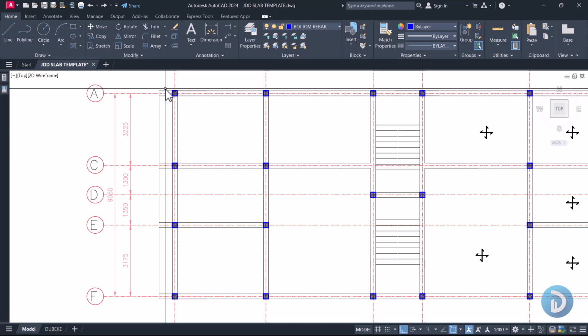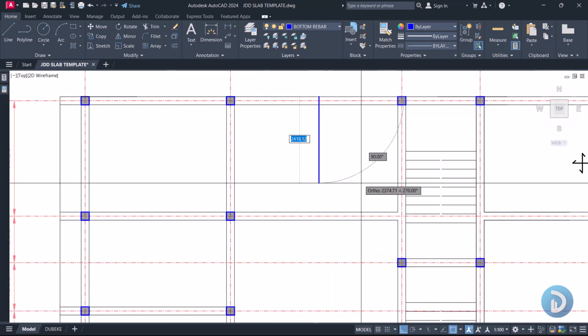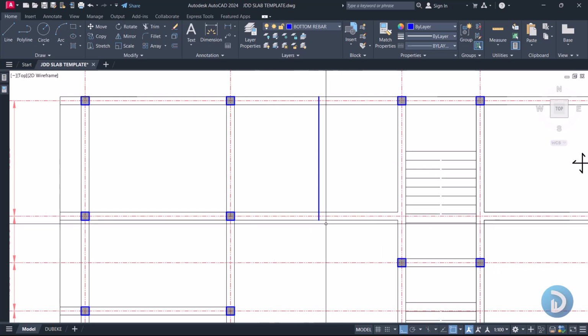Now to detail our panels, there are two basic ways we can choose to detail our slabs. We can either detail per panels, or we can detail by the length of your reinforcement. So if you are detailing per panel, we will run our reinforcements as though they run from each of the panels of this beam and they terminate at another beam. Okay, so this is the first method by which we can detail our slabs.